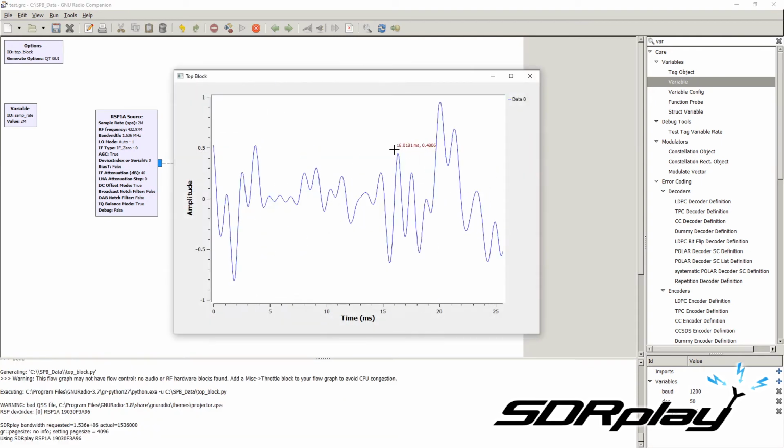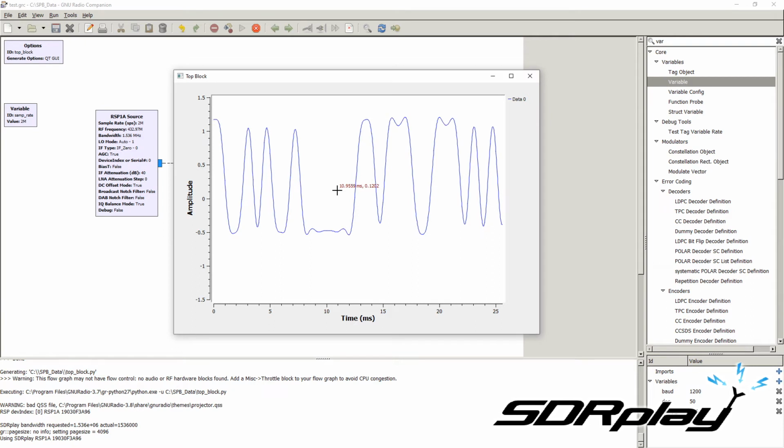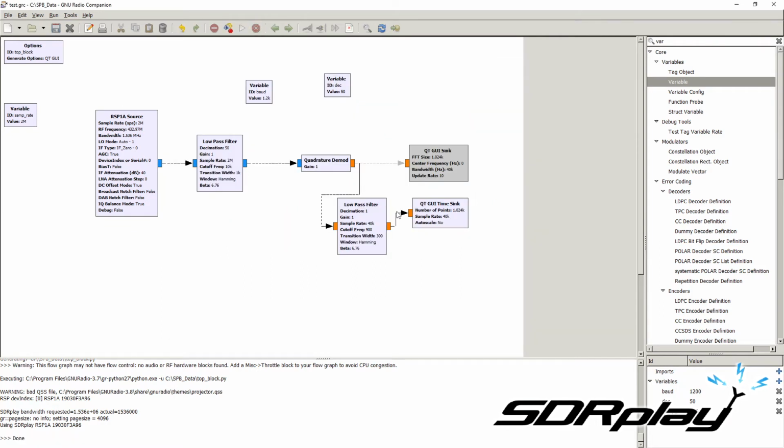If we now press play and stop on our signal, we see that the signal is heavily shifted towards one side. This means that we could get a 0 bit which is higher than 0, and this does not register as a 0 bit. To make sure that the signal is actually centered around 0, even if the frequency is slightly wrong, we can correct for the bias.